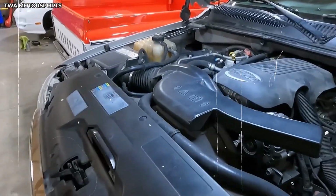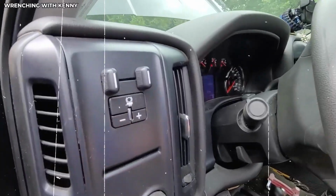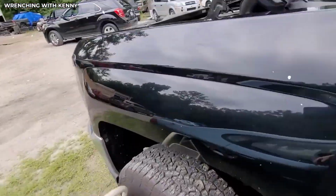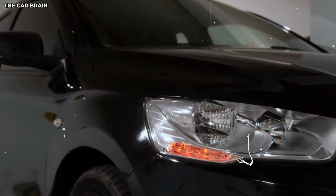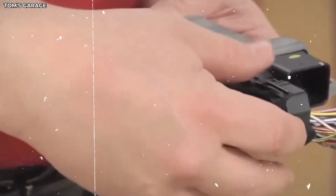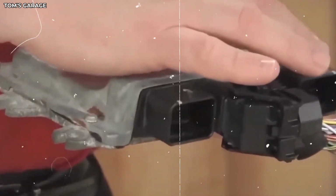Loosen the 10mm bolt on the negative battery terminal. The negative terminal is marked with a minus sign and usually has a black cable attached. Remove the cable and move it away from the battery post so it can't accidentally reconnect. Don't touch the positive terminal. You only need to disconnect the negative.